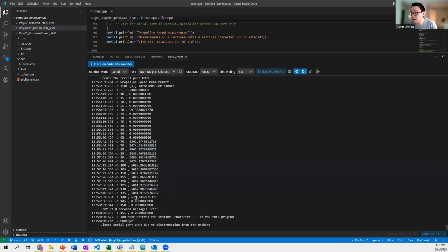At the beginning and the end of that measurement, I'm kind of just taking the blades in and out, so it's not particularly accurate at those points. Towards the tail end, I probably took the propeller blade out in that 5-second interval, and so that's why you still see some RPM calculations, but that's just at the very end of the measurement.